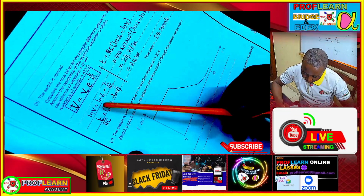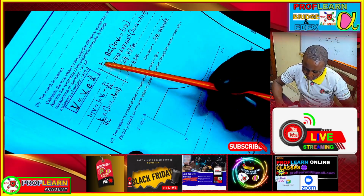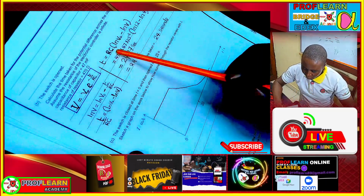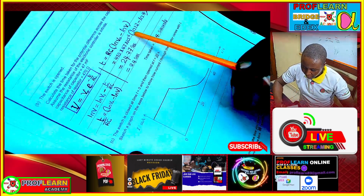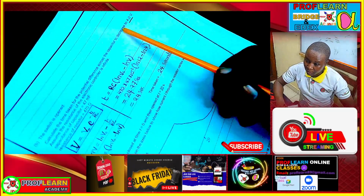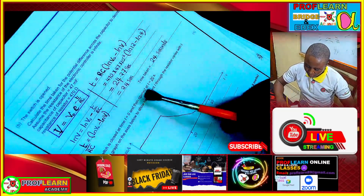And then if you rearrange this formula, guys, you are going to have time t equals RC times ln V naught minus ln V. Then if you substitute the resistance and the capacitance, which is provided here, and the original voltage was 12 minus the voltage that they are asking at this given point, the time that is going to be taken is approximately 24 seconds.